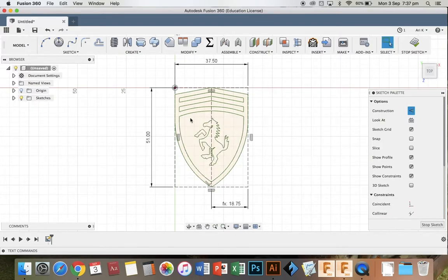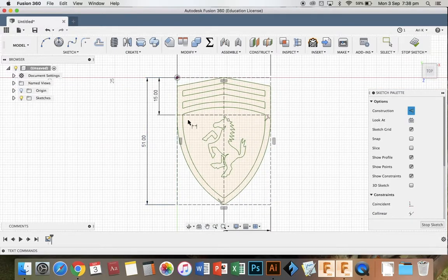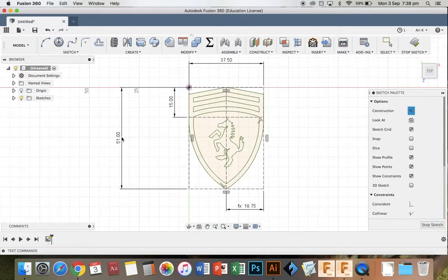Now we will put the cut line where the cap goes. We'll draw a line from side to side. Again, it is yellow, we need to dimension it. So we'll press D for dimension as a quick key on the keyboard. We'll select the other line, and then click. We'll make this 15 millimeters. Enter. Now we have the cut line for the lid of the USB. We'll neaten up the sketches a little bit, just drag them out a bit.